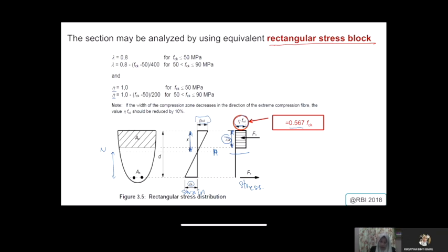This is the position of your tendon, and the tendon caters for the tension condition of your beam. When you make a straight line here, you can draw it slightly at the center of your tendon. If you have another layer of tendon, then you will have another strain, epsilon s1 and also epsilon s2, so you have two values of strain.